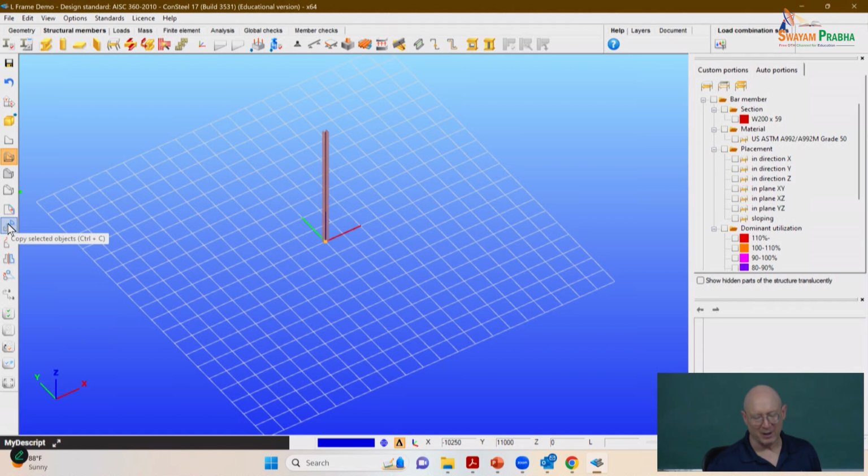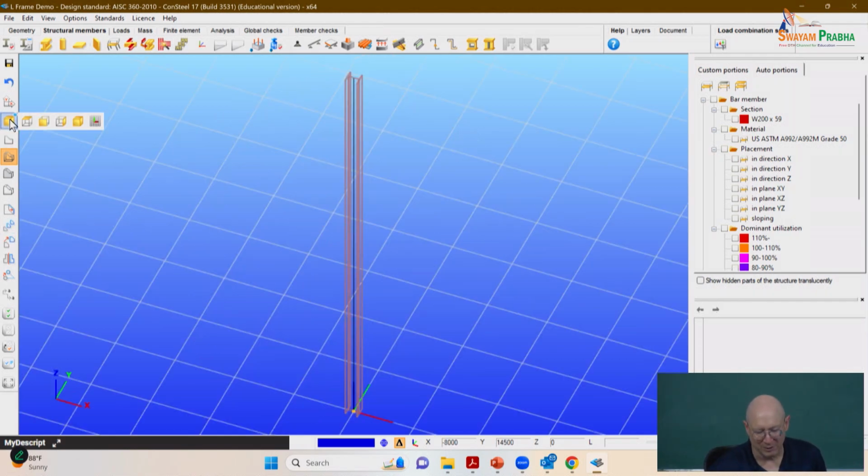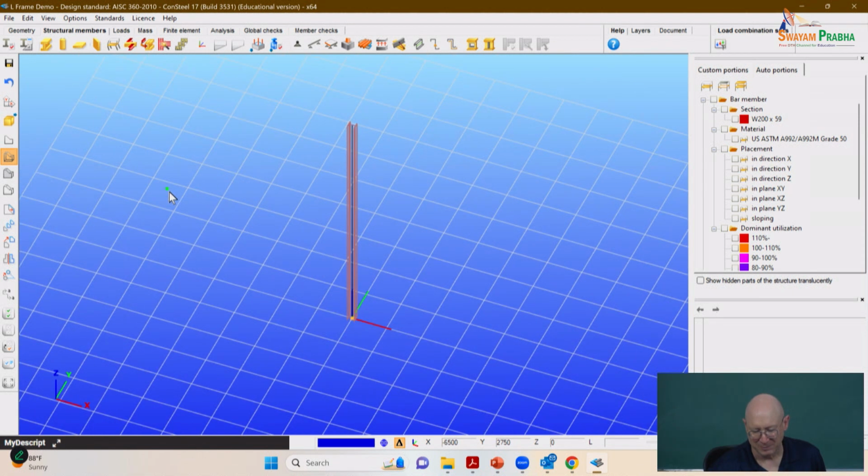So now let's go ahead and do the beam. And I'm going to actually do one thing here. I'm going to kind of set my orientation. Okay. All right, so for the beam it's actually general. If it's a column, basically it's going to give you a member that's oriented in the Z direction. If you look at the coordinate axes, they're shown in the lower left of the screen. So a column is by default Z. A beam could be any direction. Okay, it doesn't have to be horizontal.